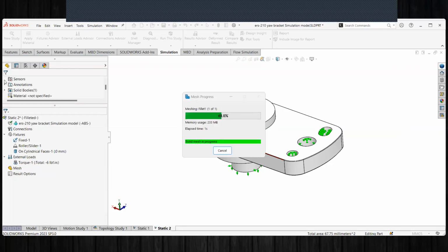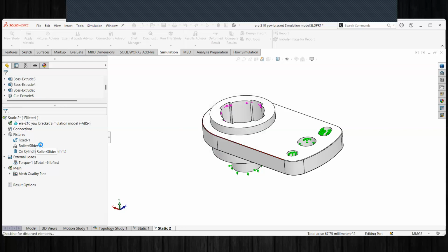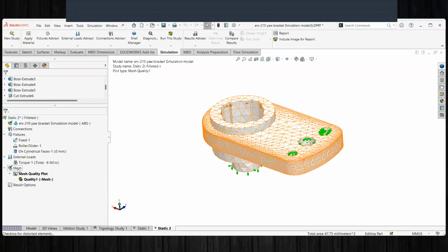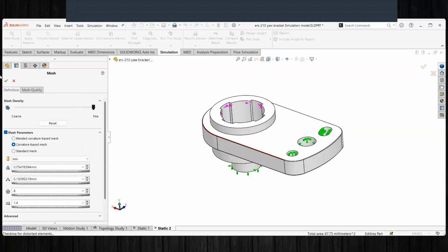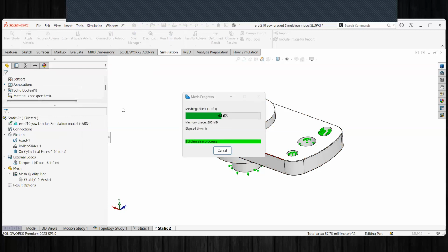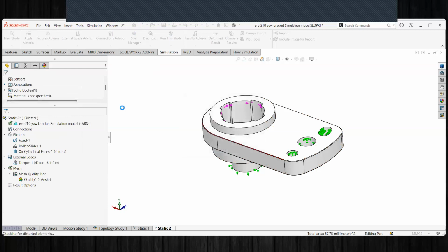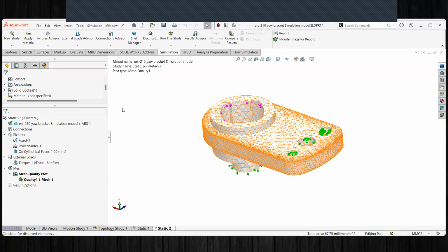So I'll mesh this thing up. Let me bump up the quality there a little bit more of the mesher. Let's see, yeah, I'll be able to bump it a little bit more. And that's what you're going to be doing as you're converging results, right? You want to converge what did we say? The geometry, add more detail; the setup, which is the materials, the way you apply fixtures and constraints; and then thirdly, your mesh. You want to start to add more detail in the mesh like I just did right now. All right, I think I feel good about this.